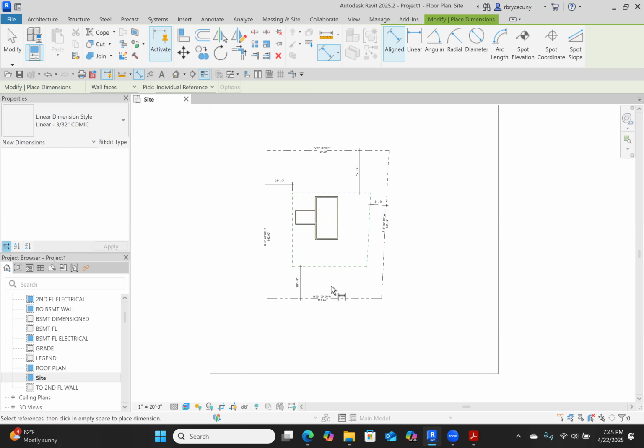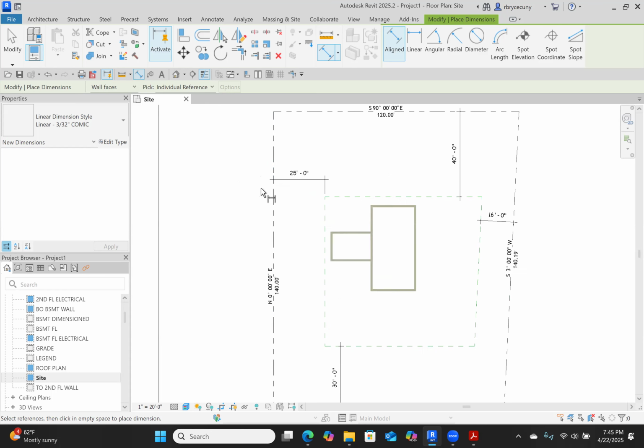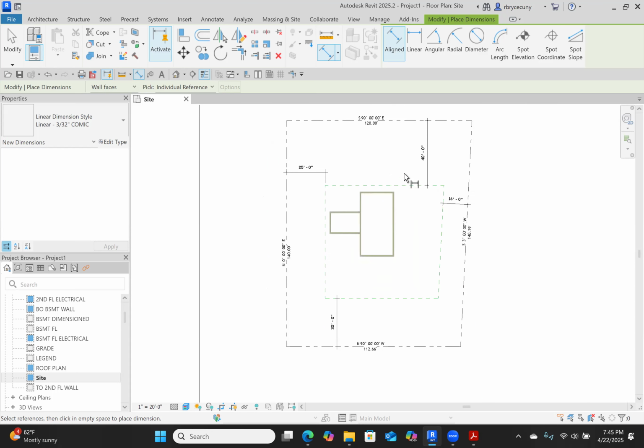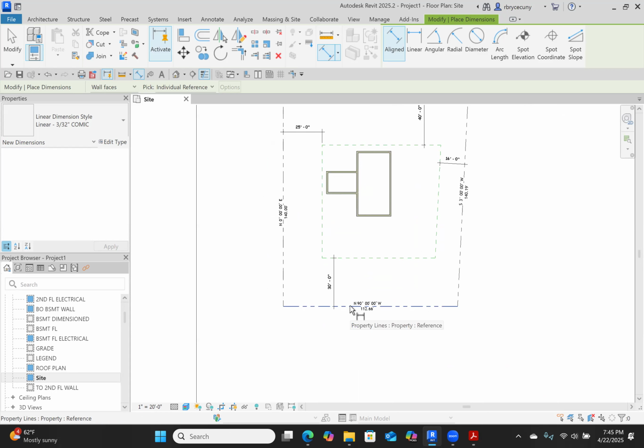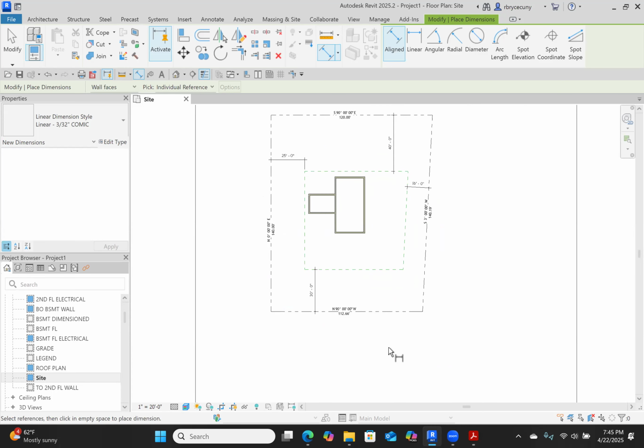And then the second thing that I would do is make sure that for the area that this house is being built, the setbacks are exactly what they're supposed to be, that I haven't made any mistake, because I don't want to start designing the house and making it fit into a building envelope that isn't accurate, because I don't want to do work twice.